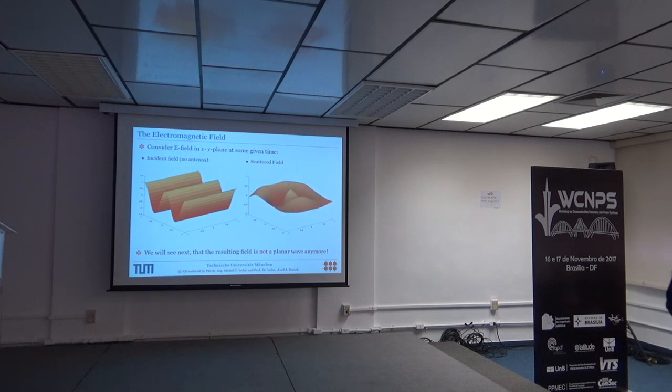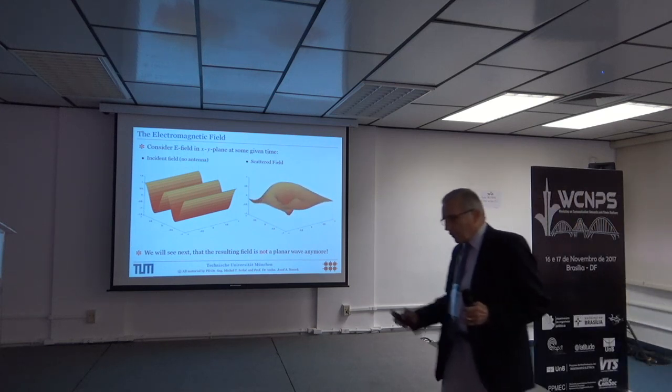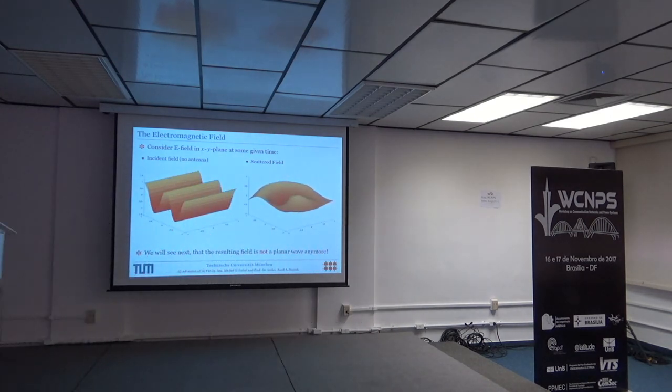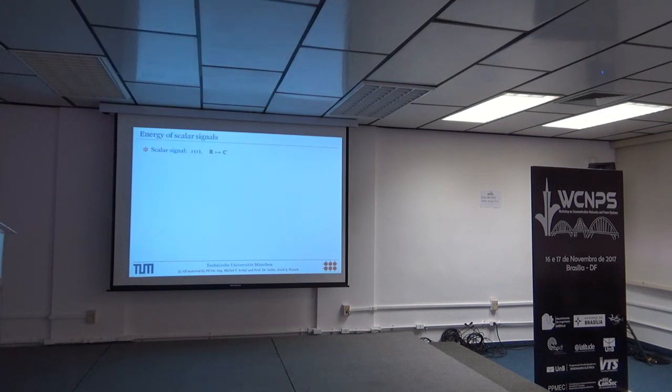When you make a measurement in any circuit, measuring the voltage from a node towards ground, as soon as you connect the voltmeter, of course the voltage will change. The change may be little. Here it's different, because we would like with our receive antennas to take much energy out of the field, in contrast to the voltmeter, where we would like to take only a very low current out. Okay. Therefore, we have to have a closer look at our physical models.